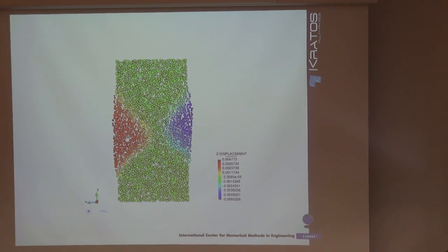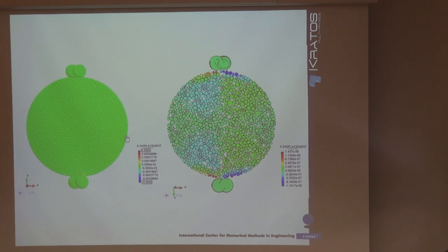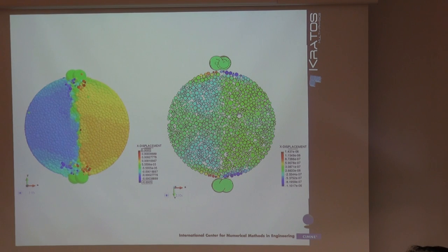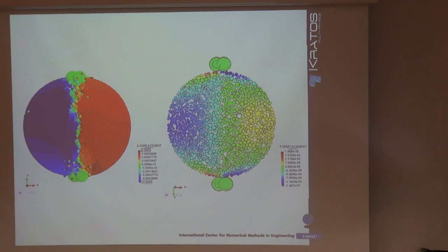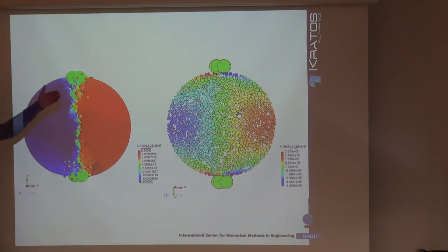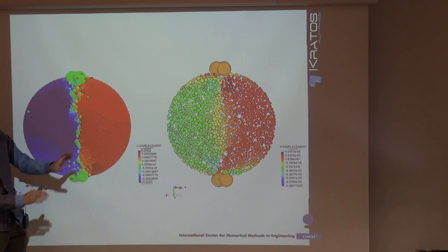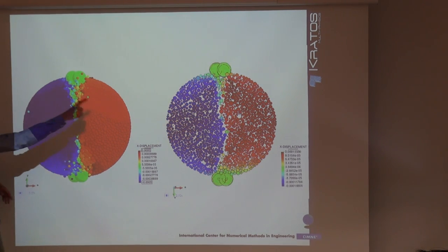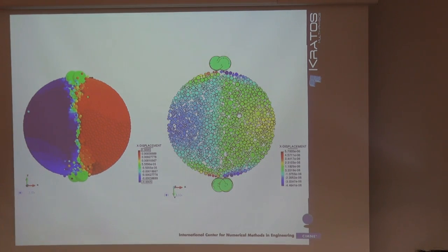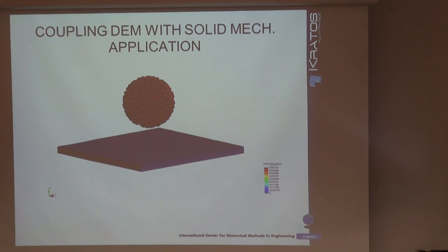So we can deal with particles with different approaches. This is just another video where we can see a BTS, a Brazilian tensile strength test. This is the 3D complete model, and this is just a cut where you can better see how the displacement and how the fracture evolves. Okay, so these are just DEM applications, but we can also couple,